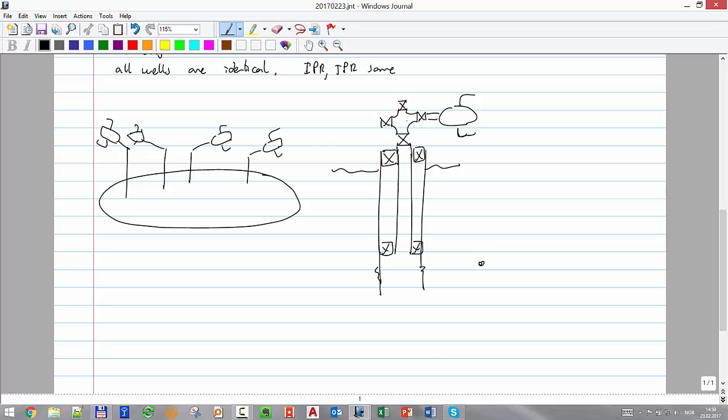So I'm going to ask you, the maximum flow that the well can produce, what we also call the potential, depends on what? If it's open choke. Separator pressure, which we assume remains constant for the life of the field, but also something else. Tubing diameter, okay, let's put that plot here. We have an intersection between that, that's TPR, if we take the equilibrium point at the bottom hole, and IPR, right?